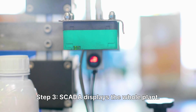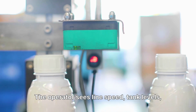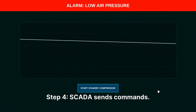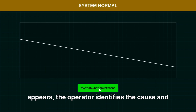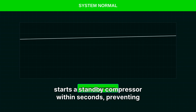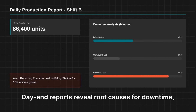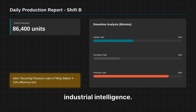Step 3. SCADA displays the whole plant. The operator sees line speed, tank levels, and energy use from one room. They can increase speed directly from the screen. Step 4. SCADA sends commands. If an alarm for low air pressure appears, the operator identifies the cause and starts a standby compressor within seconds, preventing downtime. Step 5. SCADA records data. Day-end reports reveal root causes for downtime, like recurring leaks, converting raw data into industrial intelligence.